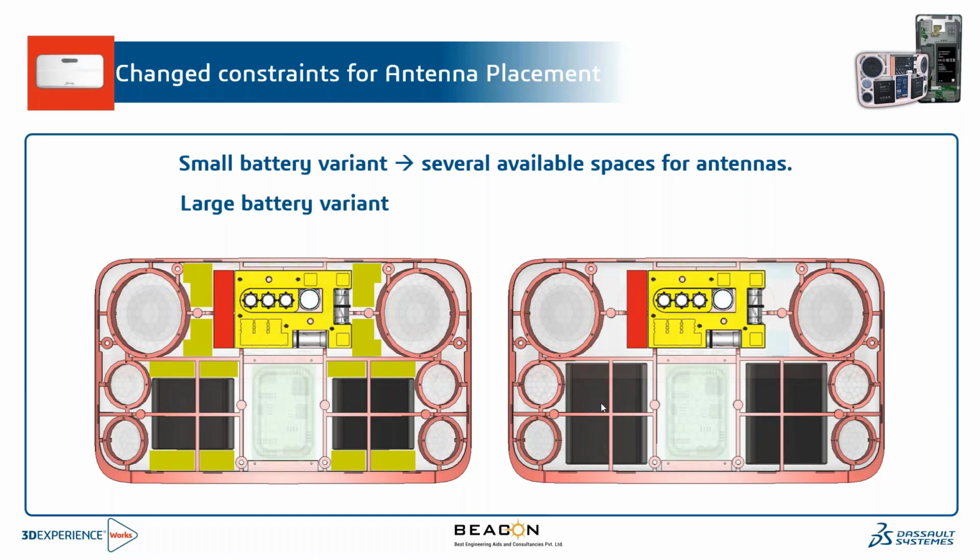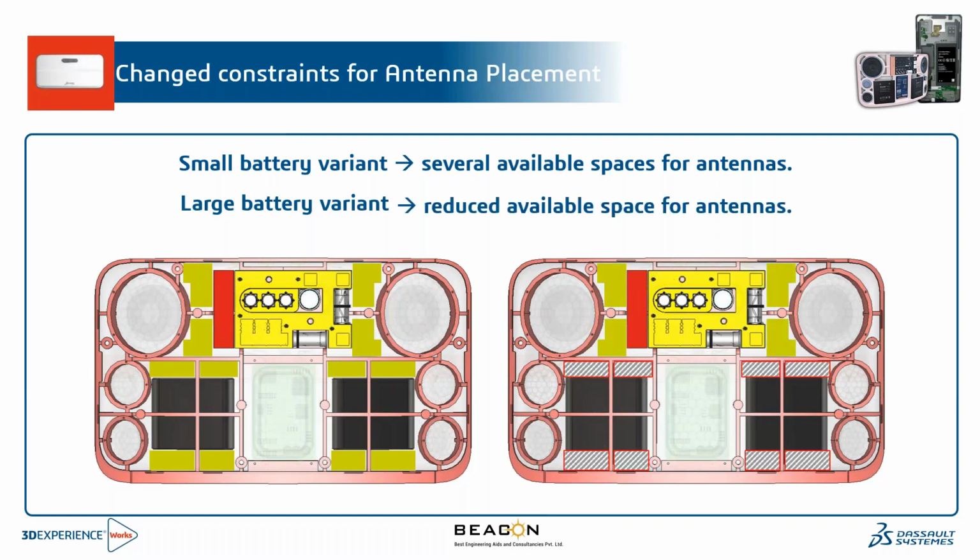That is, we need not go through a certain reference paper, or go to any customer or the shop to get the data sheet of a certain type of antenna which suits the requirement for my design. I can make use of Antenna Magus. In a short time, I can choose the type of antenna which is suitable with respect to the filters available within that, and I can start placing the antenna and check its performance rather than looking for which type of antenna will best suit my design. That is one of the added advantages of making use of Antenna Magus in CST to perform this type of analysis.